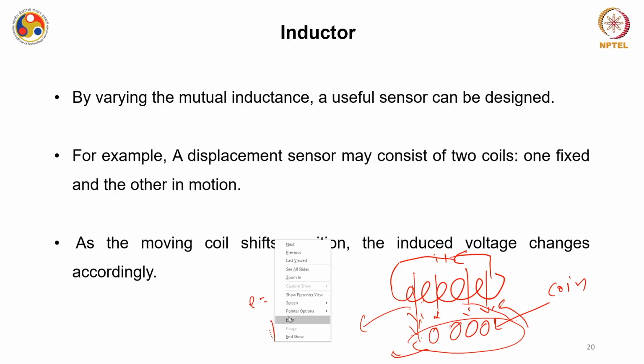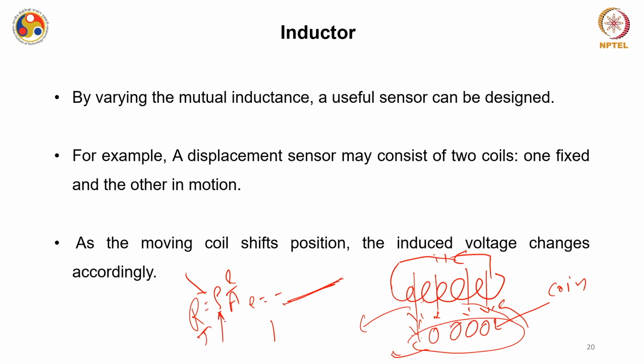The resistance is simply defined as rho L by A, where rho is resistivity, L is the wire's length, and A is the cross-sectional area. We will see that this resistance can be changed by either changing rho, or changing the area, or changing L. This rho is usually the property of the material, so we will focus on L and A. Similar to inductance and capacitance, we will also define a geometry factor, and we will see how the resistance value changes if the geometry factor changes.